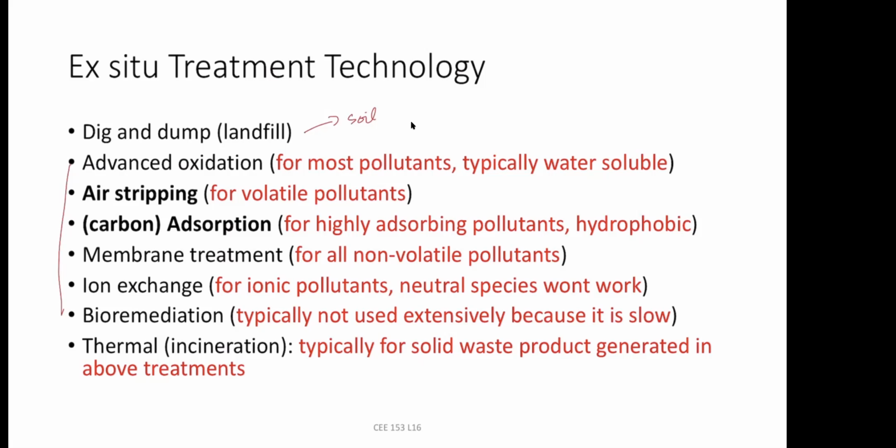What you have got to remember is when each system would be more efficient. So think of advanced oxidations. Anytime I ask whether this is efficient or not, as you see, advanced oxidation means the pollutant has to be oxidized. So if you have a compound that cannot be oxidized, you can't use this method. So you have to think of what you are using. Can it be oxidized or not? If it can, then this method would work.